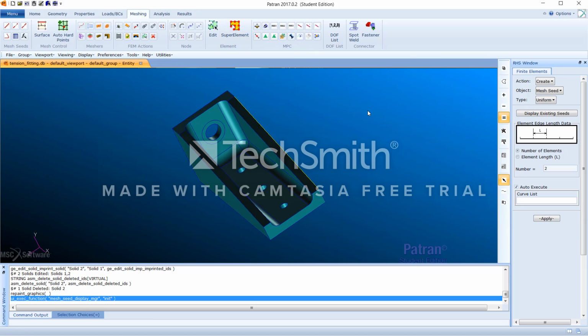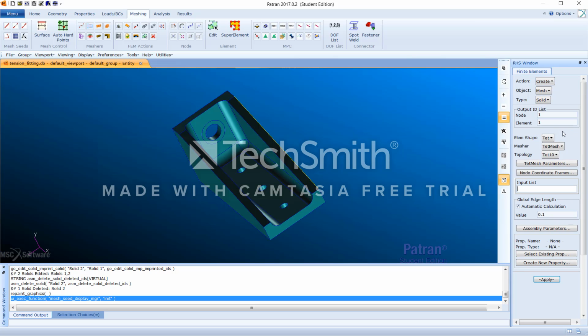Now we are going to create a TET mesh for the tension fitting. Set action as create, object as mesh, and type as solid. Make sure that TET mesh and TET 10 are all selected and apply it.